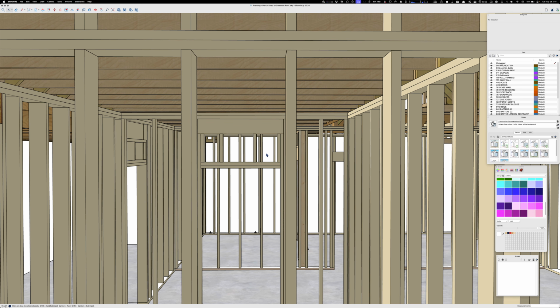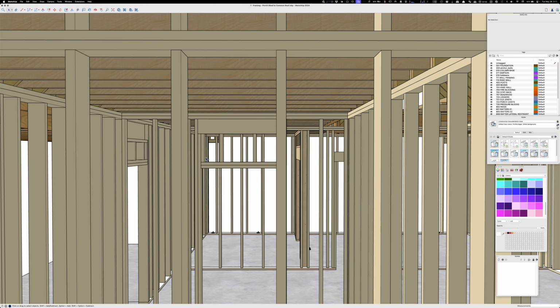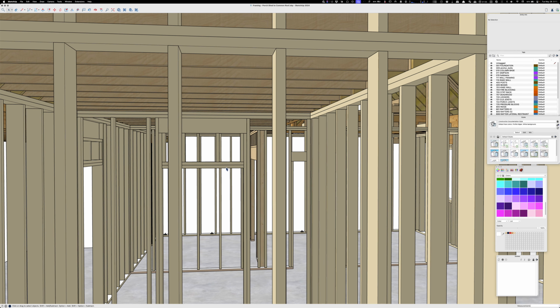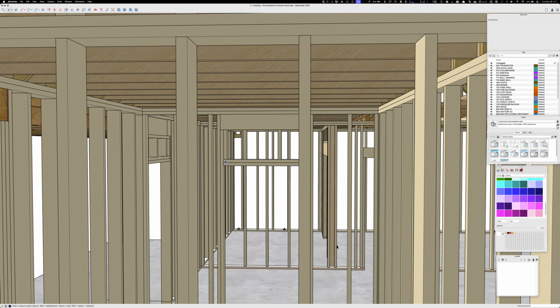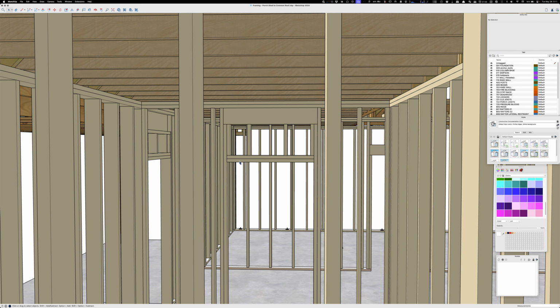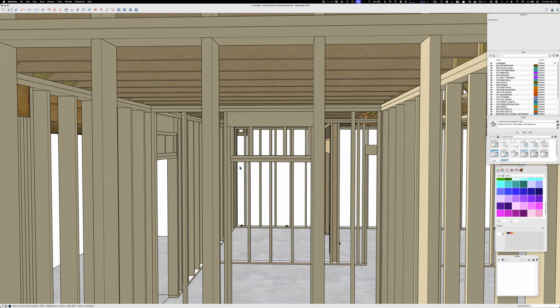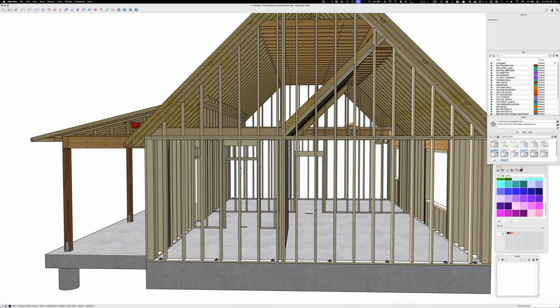We had to tear them all out and put new trimmers in, or cripples, what do you want to call them. So I learned on that job, put the headers in all the way and block down, because it's so much easier to take off. And I double bottom plate now too, because if I just need 1.5 inches, I just rip that one plate off and I'm done. So not going to catch me again.